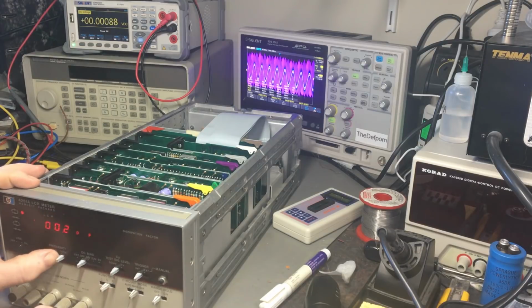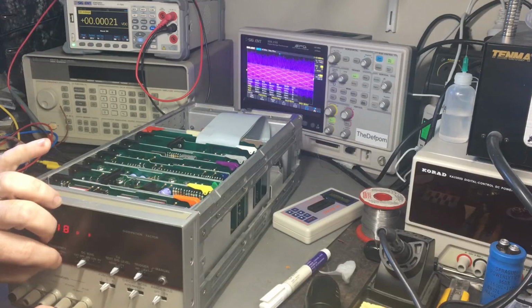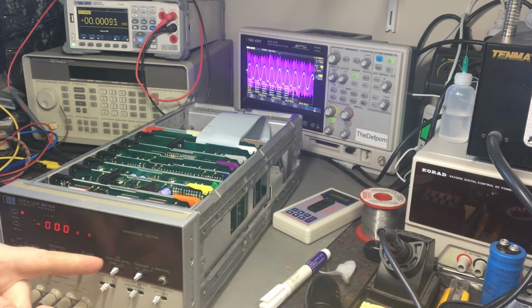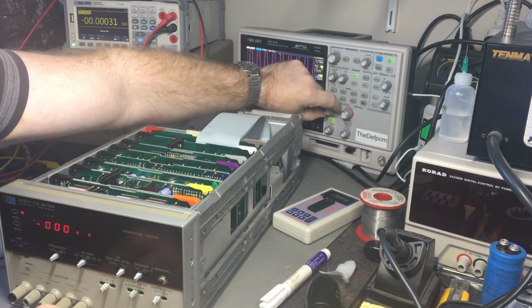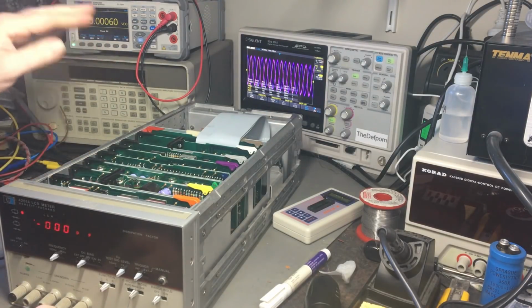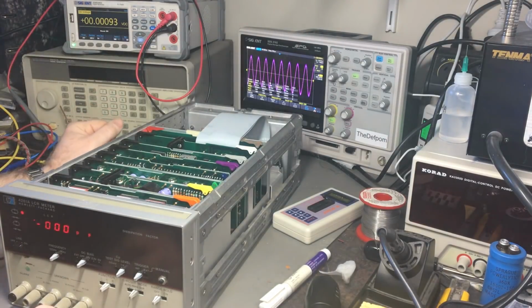Yeah, thereabouts. 1 kilohertz is also about 48. So yeah, that's okay. The voltage level at that point looks alright. So I need to do a 1 volt level. So drop this down a bit, because that's only 50 millivolts, so any little noise in there was showing up quite badly. It's been triggering up. There we go. So that's showing us a much higher frequency, interestingly.